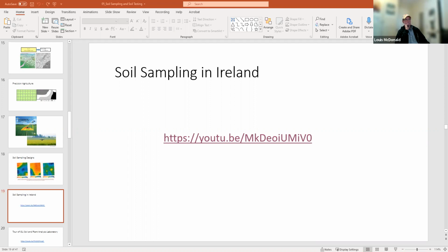It's very, very important to be organised and prepared. For example, what we use mainly in this country is a funnel type of auger. And it's a 4-inch core. It's a conical shape, narrow in the base and wider in the top. This allows the soil to move up in the core. Now we must get a 4-inch core every time.